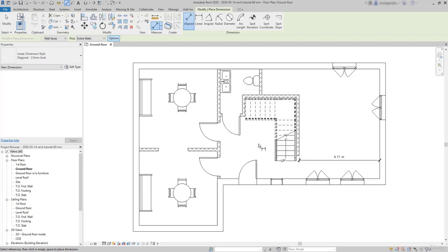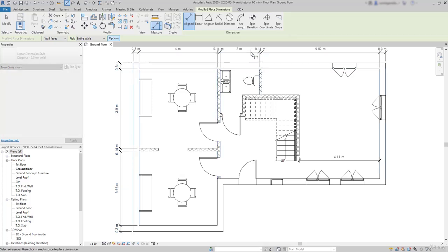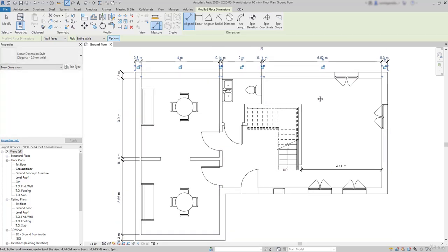Click OK, select the wall, and I'll automatically create segments when walls are intersecting. This is very nice because it allows me to avoid adding dimension lines manually, which could take a long time for large buildings, like a hospital or a hotel. Now, if I want to do the same for the wall above, I'll just click there right away. When I finish adding dimensions, I press Escape. Don't press Enter because it doesn't work.